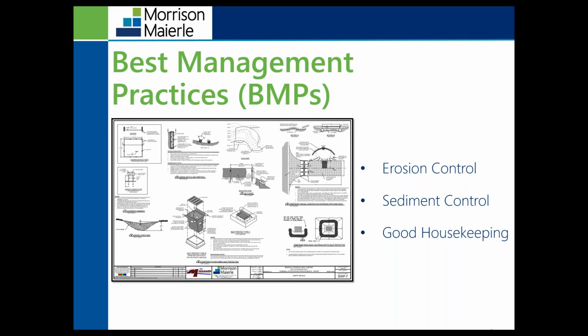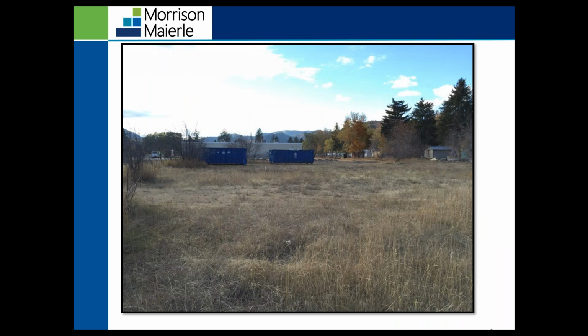So we're just gonna go through some examples of BMPs. When you're preparing a SWIP, these are BMPs that you're gonna be calling out potentially to minimize the pollutants from discharge. So the first one is a picture of natural vegetation. It's an erosion control BMP. The purpose of this BMP is to protect existing natural vegetation within the construction site, to minimize the amount of bare soil exposed to erosion, reduce the velocity of stormwater runoff, reduce the erosion and raindrop impact on the soils, allow water to permeate through the soil, provide a buffer and biofiltration, and be aesthetically appealing for a construction site.